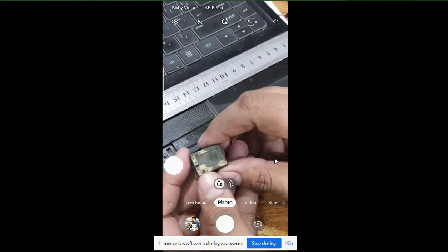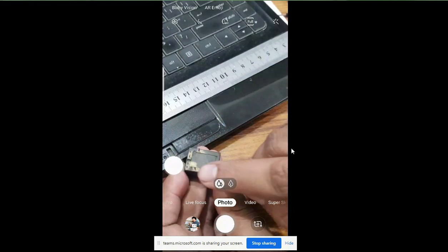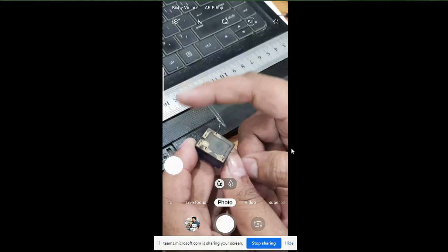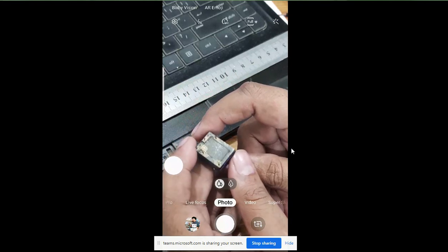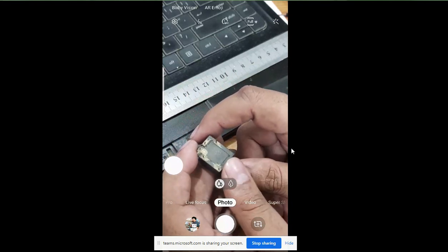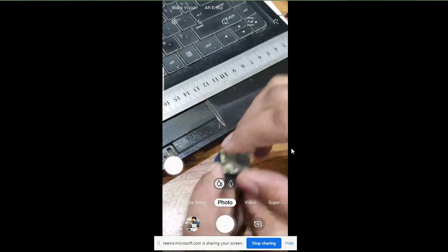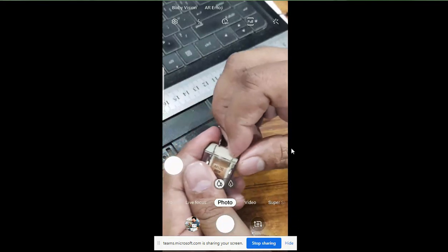It's a little different nomenclature over here. You can see again there are 1, 2, 3, 4, 5 pins. Now these 5 pins are certainly, 2 are going to be coils, 1 is going to be the common, and the other 2 are going to be normally open and normally closed. We can verify this with the meter as well, but here I am not going to talk about this one first. I am going to talk about this 12 volt relay first over here, because we want to make this contact over here.